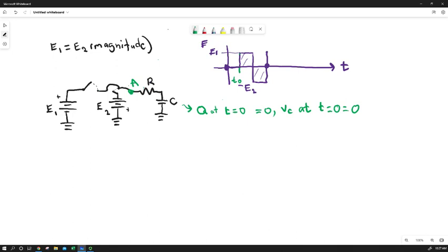As we know, a capacitor is going to act like a short when we have a very fast change in voltage, which definitely a step function would be. So we'd have all of our voltage drop over the resistor. But as the capacitor accumulated more and more charge, it would start to effectively push back, and we would end up looking at its response coming up very quickly and then leveling off. This line is our V sub C, which is a function of time.